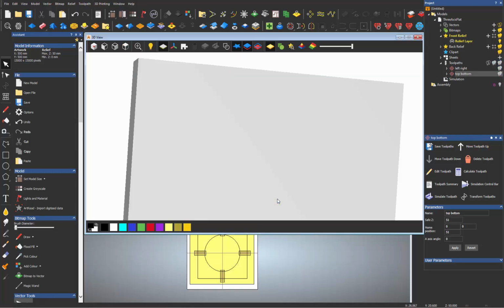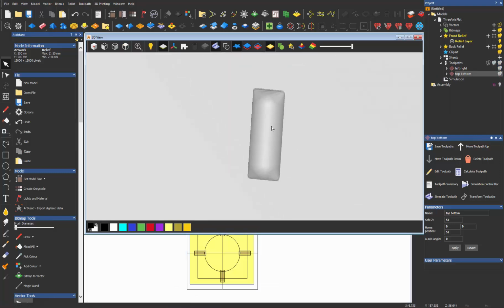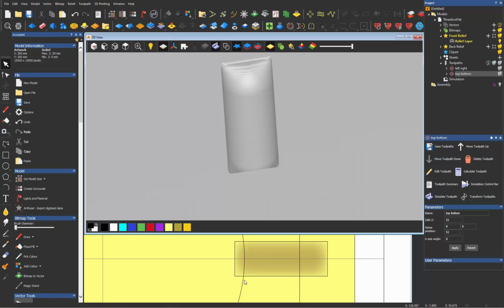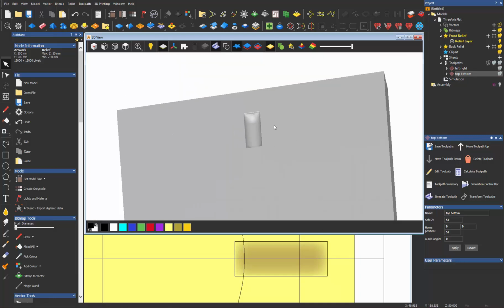Okay, we'll just do a fast one. So anytime you do something with a ball nose, you always have the radius of the end of the tool to contend with. So if it was to have stopped right here, that radius would be inside this pocket. But by having it come out further, we can get it to where all of this shading here, which would be all of this, is outside of our part. So we don't have to go in and do anything special with that.